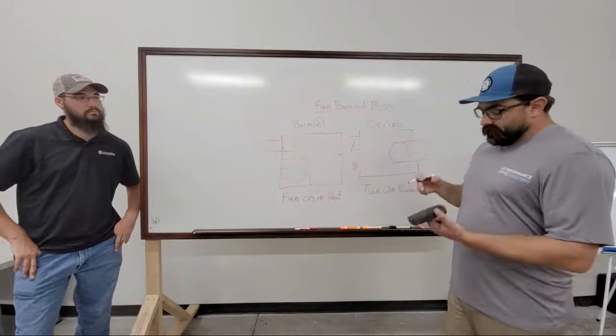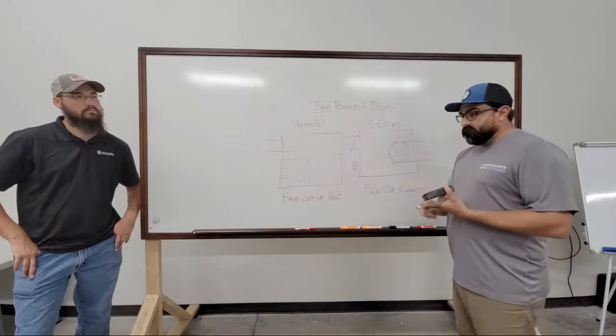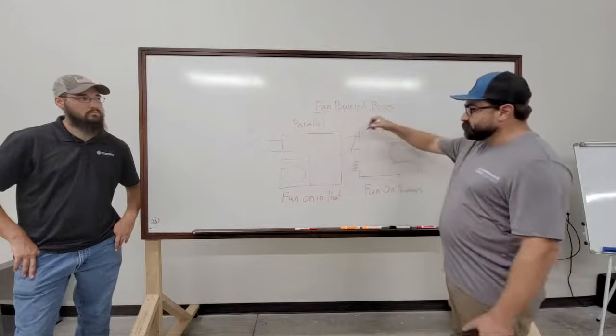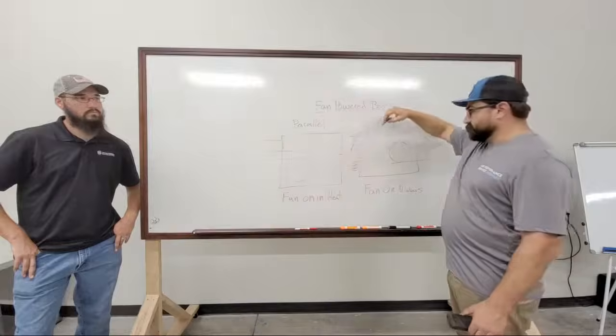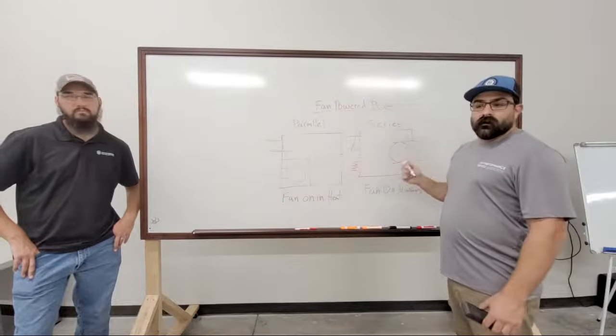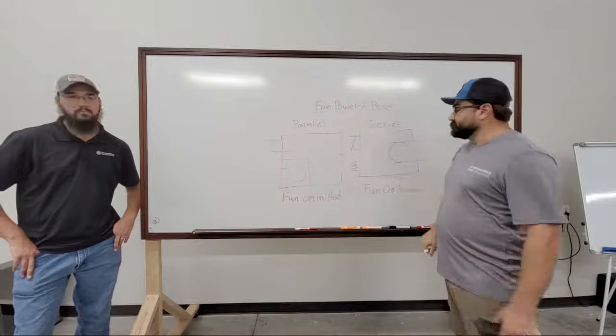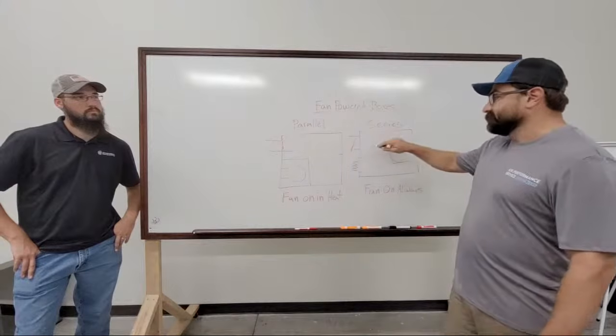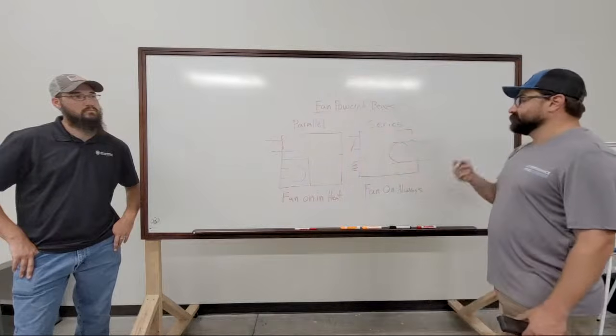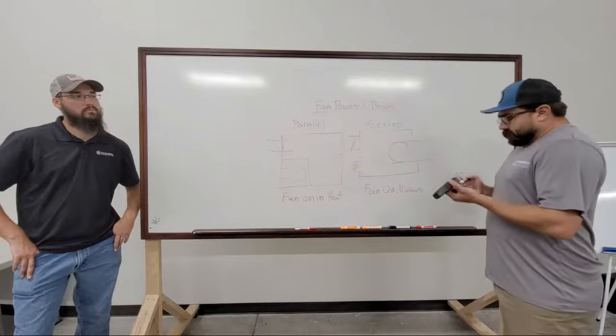That can be caused either by the fan being completely off, the fan being too slow, someone has messed with the flow set points, or someone has messed with the fan speed. Or it can also just mean it's out of calibration. So I guess there's technically three things that could cause it.